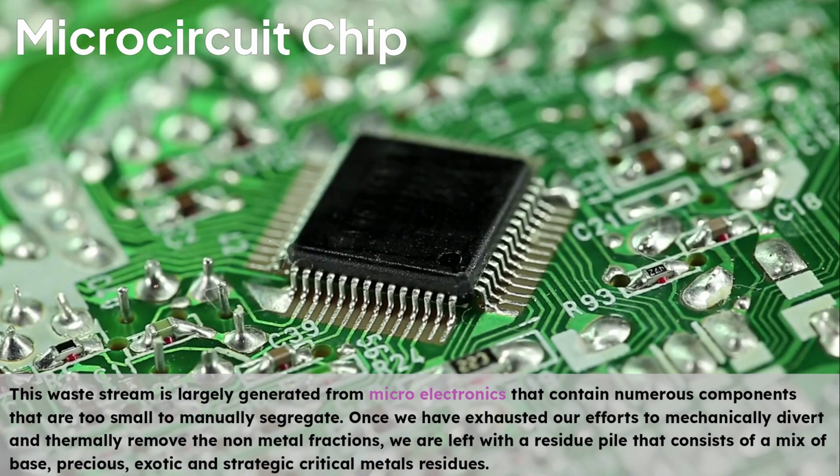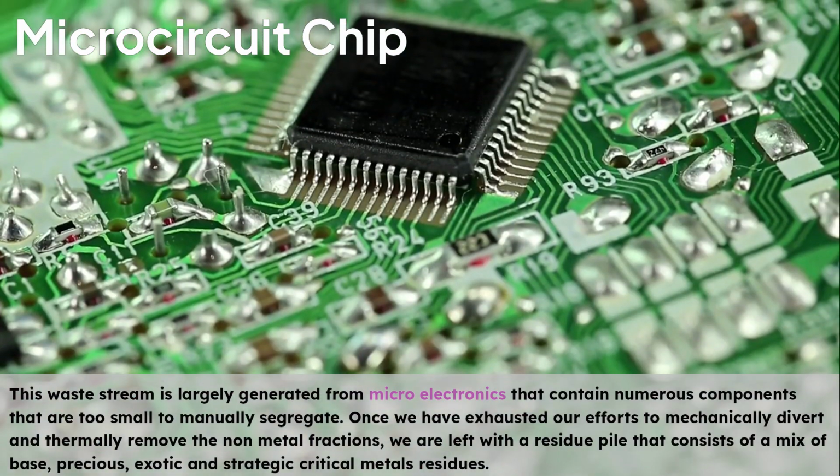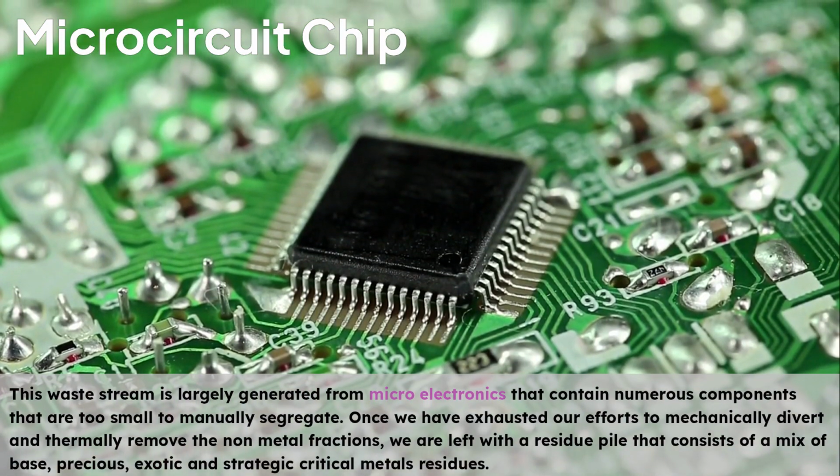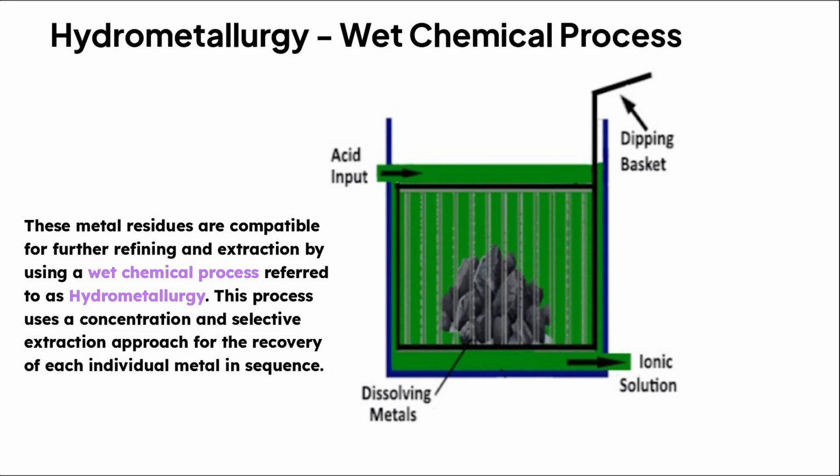Once we have exhausted our efforts to mechanically divert and thermally remove the non-metal fractions, we are left with a residue pile that consists of a mix of base, precious, exotic and strategic critical metals residues. These metal residues are compatible for further refining and extraction by using a wet chemical process referred to as hydrometallurgy. This process uses a concentration and selective extraction approach for the recovery of each individual metal in sequence.